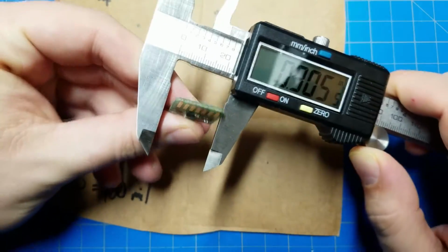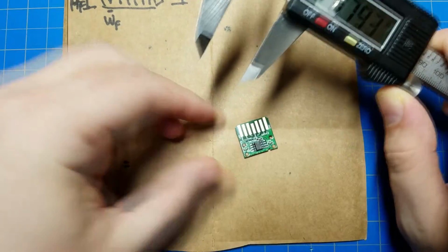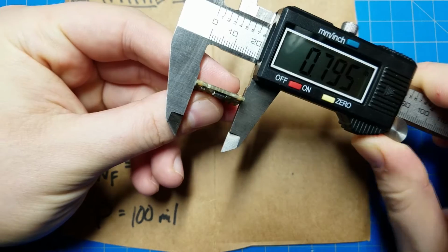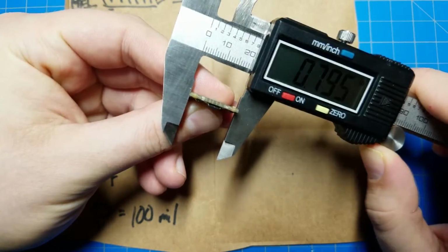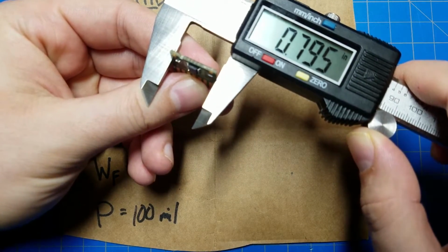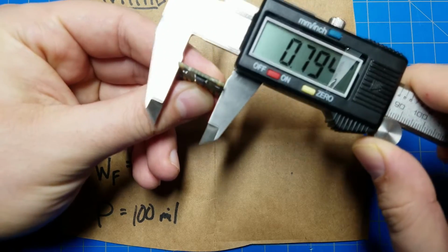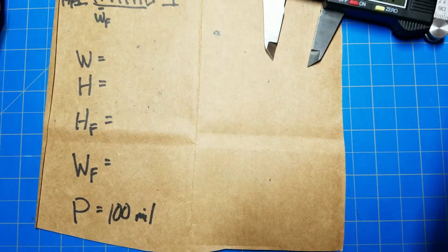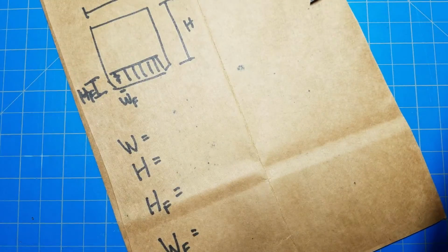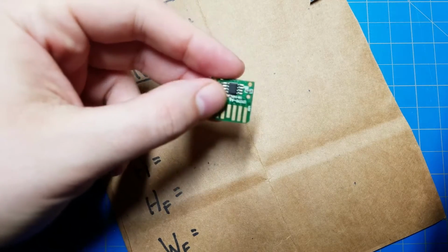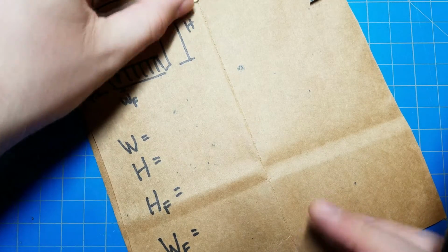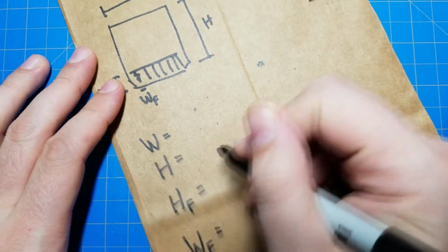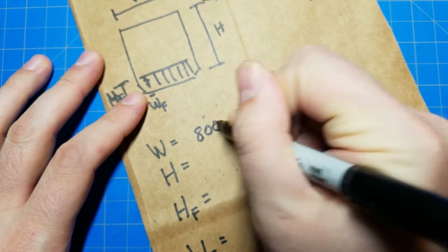The width here. And I should say, you could do this in millimeters. In fact, the first personality chips I designed, I took my measurements in millimeters instead of mils. It still works out just fine. You're just looking for a rough sense of what the size is here. So I can see it's about 800 mils. I'm going to go for round numbers here. There'll be tolerance issues. They won't be exactly 800 mils because the tool that cuts the PCB out might shave just a little extra off. But we have a width of 800 mil.